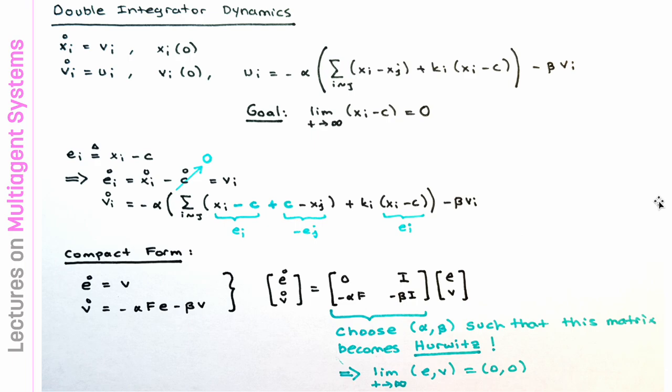Of course, if you are performing a complex maneuver, they are not decoupled, but if you are carrying loads, driving passengers from here and there, mainly you can approximate your roll and pitch dynamics as double integrator dynamics. Likewise, for your altitude problem, you can adjust your vehicle's height based on double integrator dynamics. So double integrator dynamics is one of the most important high-order dynamics when we deal with multi-agent systems.